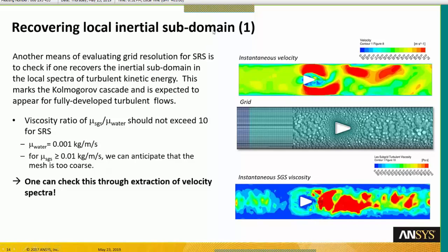How to check? Okay, I have some idea of the LES sizing in my LES region. I know now that I must feed some turbulent content at the inlet or at the interface between my RANS and LES calculation, but how do I check afterwards the quality of my results? Are there some indicators to evaluate this? So here you have a first indicator. In this situation you have an obstacle, you have some flow arriving at this obstacle, creating some wake flows. And we expect this wake to be turbulent if the inflow velocity is sufficiently high.